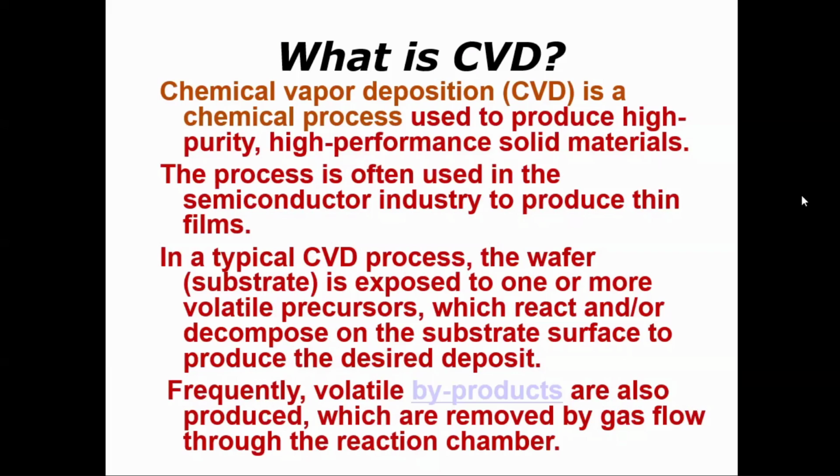Now, one thing we must have seen in the first 2 methods, that is laser ablation and sputtering technique, is that the substrate was not heated. The substrate was left as it is. Right? We just used to place the substrate in the assembly in the chamber, and then after the target atom was melted and evaporated, it was allowed to fall on the substrate.